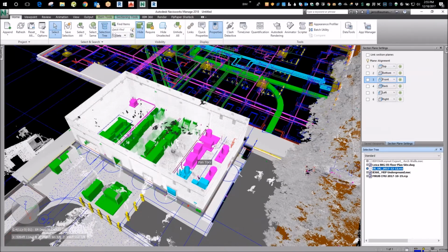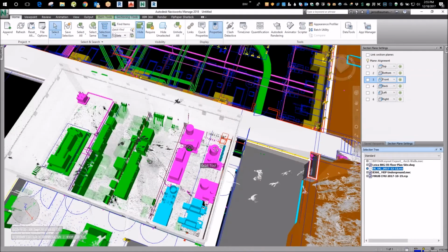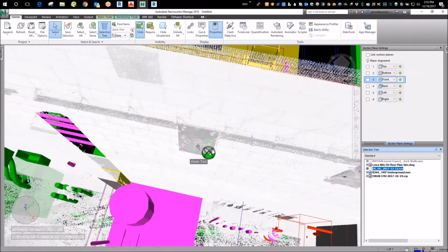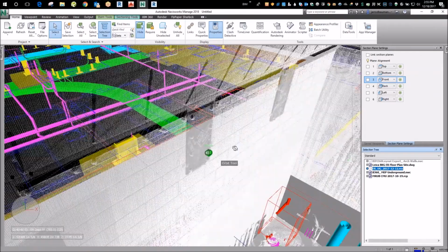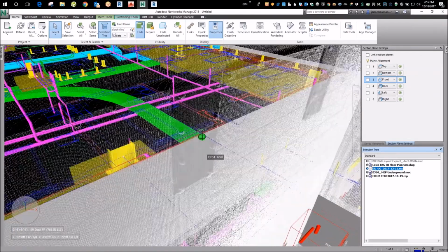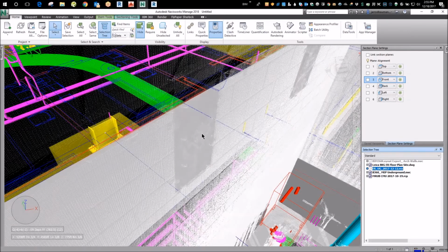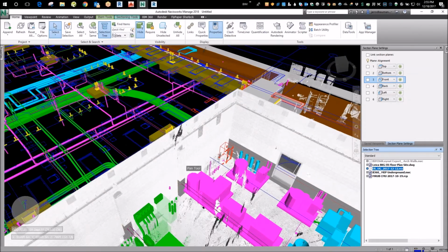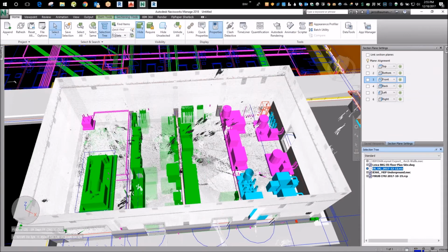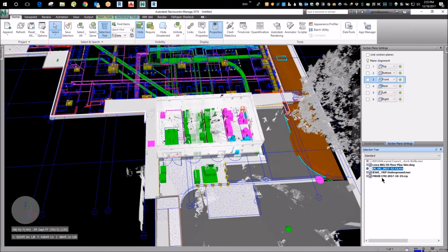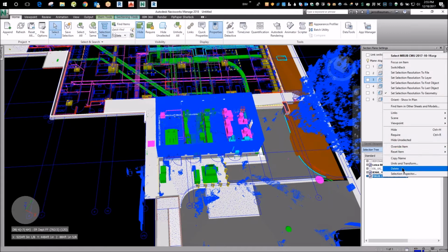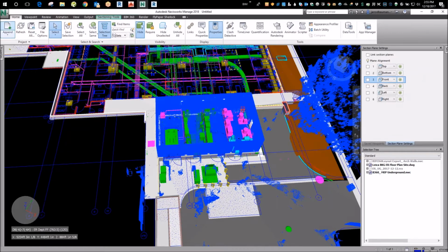So now here's the CMU from the make ready, and you can see embeds and everything. We can check. On that one, you can almost even read their chalk pen on there, as far as the embed number and all that. We checked all the embeds on this to see if we were going to have any issues, too tight, where the beams weren't going to drop in. So that was one we did. Let me pull that one out of there. Delete.